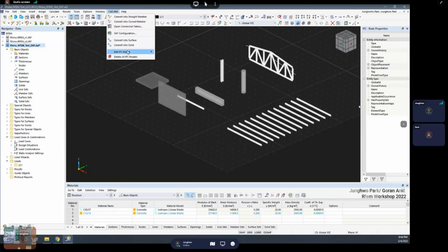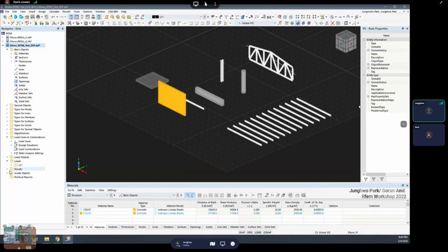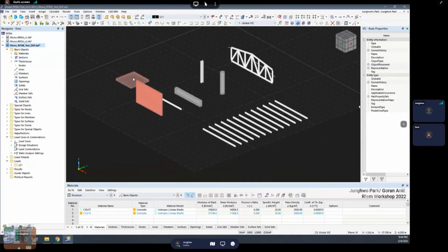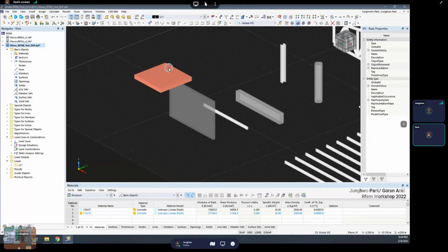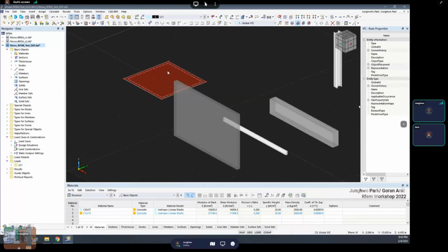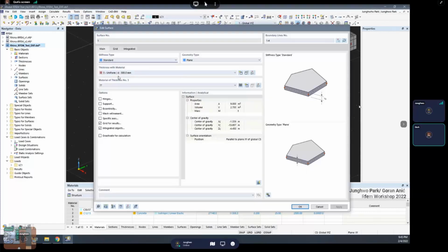Now this is the CAD beam menu. But this is the geometrical model, right? It's not a static model. Yes, this is the geometrical model. That's what's interesting, because now when I choose this surface and right click on it, I can choose an option like convert into surface or convert into solid. If I say convert into surface, that's really cool. He will convert it into a surface.